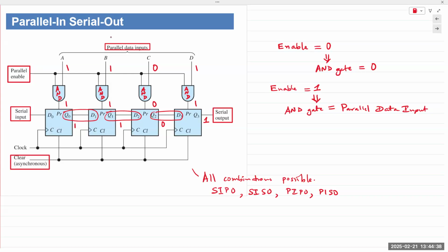A USB connection has 4 wires: plus 5 volts, 0 volts, so power supply lines, and then 2 data pins, D plus and D minus, data plus and data minus, to complete the connection. If you have a cable that only has the power lines, you can only use the cable for charging. You can't use it for data transfer. Depending on the manufacturer, some cables are able to convey data using the D plus and D minus lines. So you can connect your phone or tablet to a computer and use them as an external drive. That's where USB comes from.